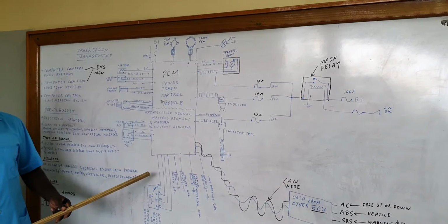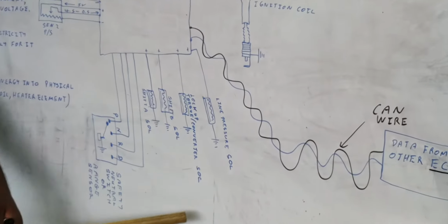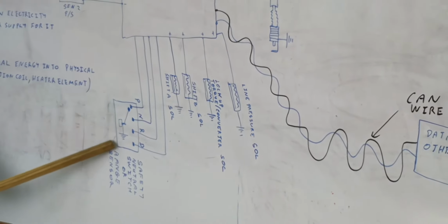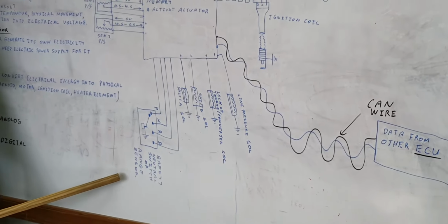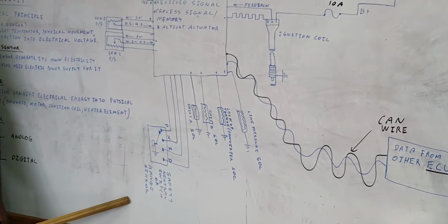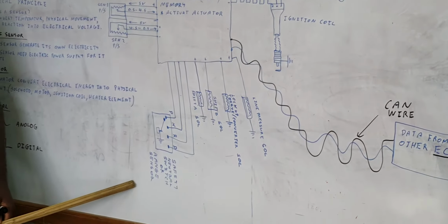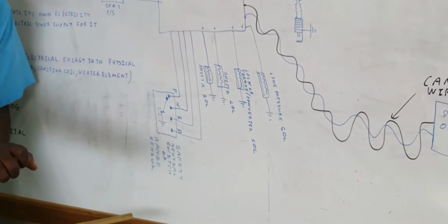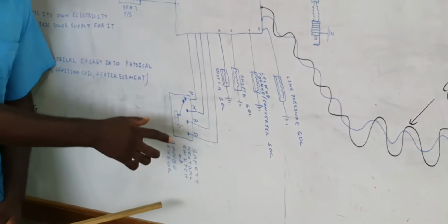If you look down here, this is the transmission side. And notice now, what is this component right here? Gear switch. A switch or range sensor. A range sensor. So when you're in your vehicle and you're changing P, neutral, reverse, D, this is what is moving.